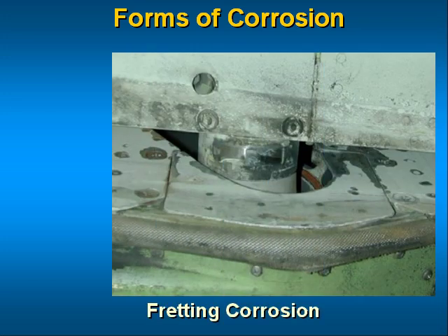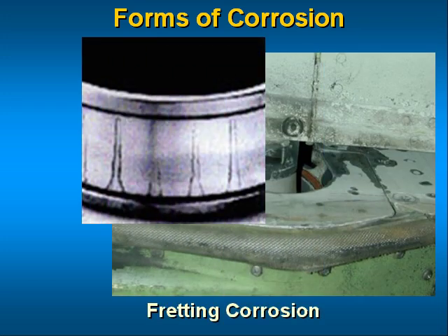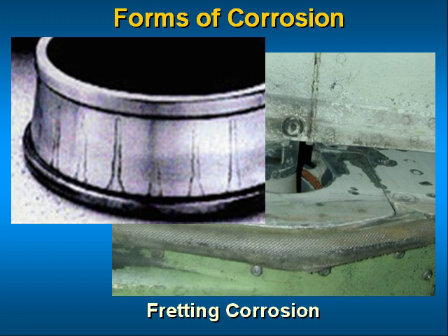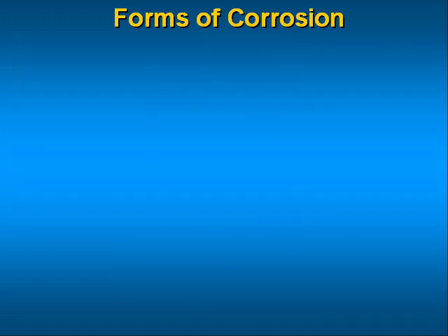Fretting corrosion. The rapid corrosion that occurs at the interface between contacting highly loaded metal surfaces when subjected to slight vibratory motion. This type of corrosion is most common in bearing surfaces in machinery such as connecting rods, spline shafts, and bearing supports, and often causes a fatigue failure. Fretting corrosion is greatly retarded when the contacting surfaces can be well lubricated, as in machinery bearing surfaces, so as to exclude direct contact with air.